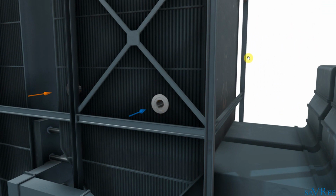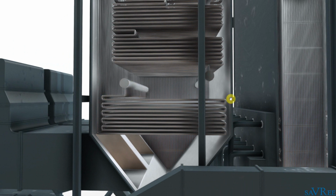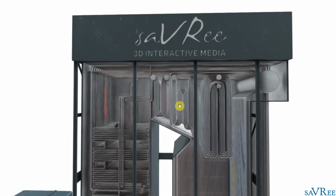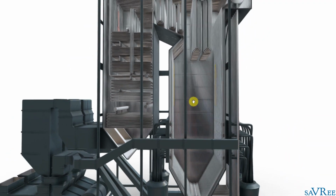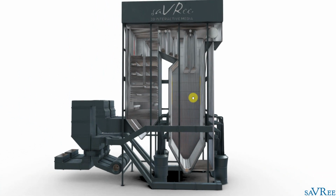It's passed through the economizer. You can see it flowing through here. This entire bank of tubes is known as the economizer. And then it's going to be sent up all the way to our steam drum by going along here and across to our steam drum. I'm going to stop the video at this point because round about now we're generating some steam. Not much, but that's what the rest of the boiler is for.